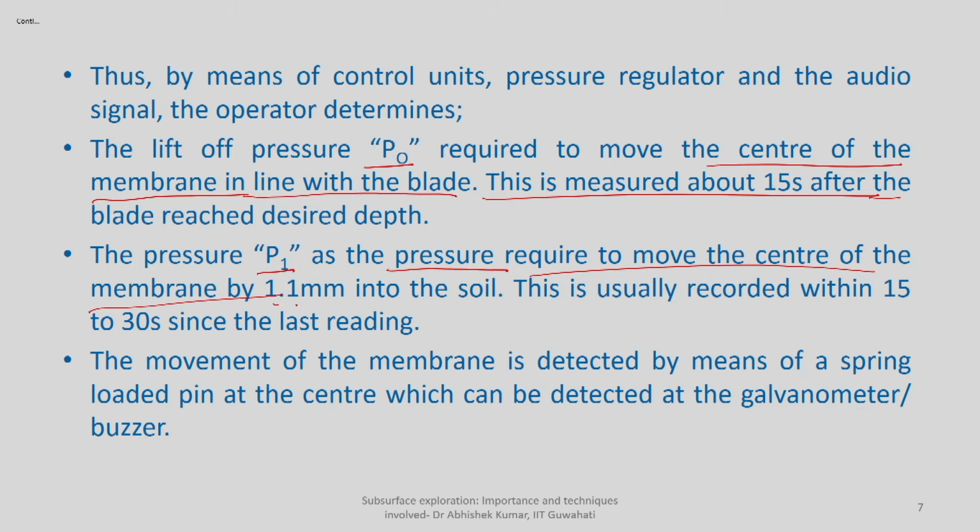In the second one, you are actually pushing the membrane away from the blade such that the deflection at the center of the membrane becomes 1.1 mm, indicating that you have pushed the surrounding soil by 1.1 mm. That is a way of measuring how much resistance the soil offers against this constant deformation of 1.1 mm. This is usually recorded within 15 to 30 seconds since the last recording.